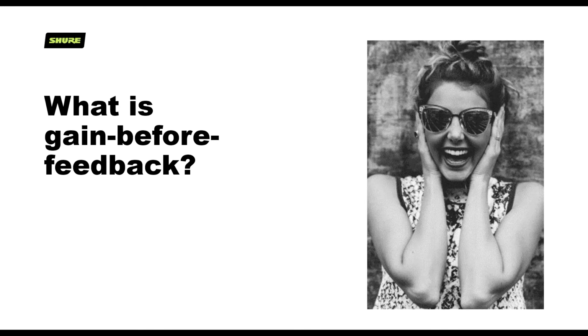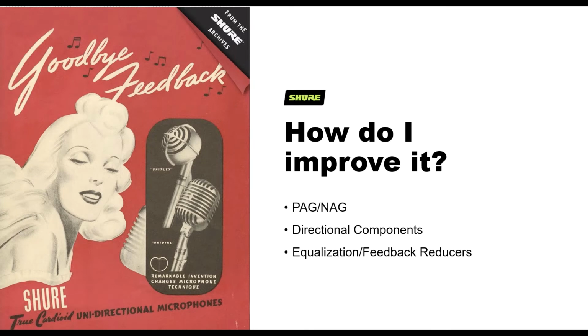What is gain before feedback? The last time we did this webinar, we had originally titled it Maximizing Gain Before Feedback, but we decided to change the title because we realized that might not be a term people are familiar with. But that's all gain before feedback really means: how loud can I turn up my sound system before I'm going to get feedback. So when we talk about maximizing gain before feedback, we're talking about optimizing our sound system so that we can get the most possible level or gain before feedback starts to occur. So how do I improve it? That's what we're going to get into next.